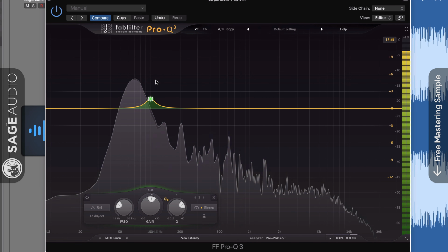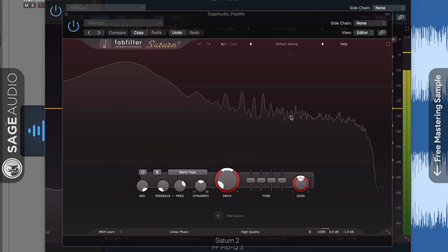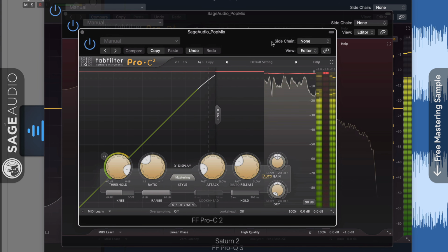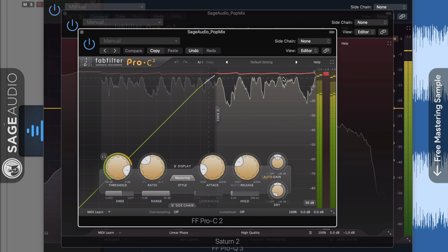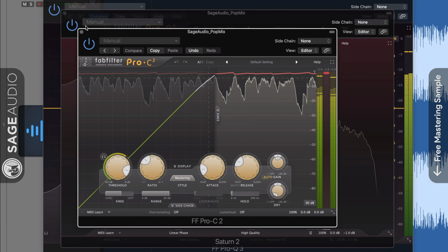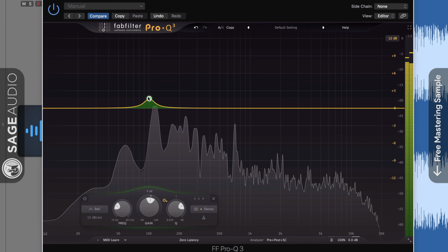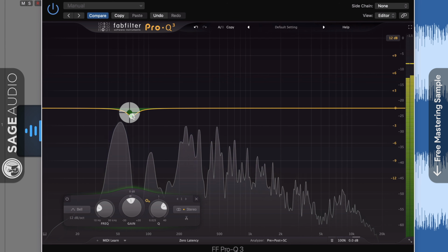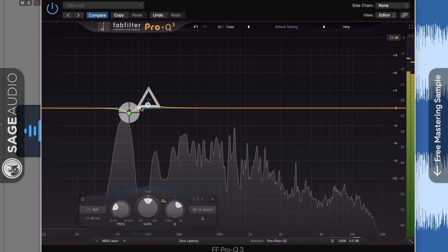Secondly, that 100 Hz wave is now running into the next stage of processing a little more aggressively. For example, if the next processor is a compressor, then 100 Hz will play a more significant role in how much is compressed and when the signal triggers the compressor. Again, this may not be something that you want. Instead, what we could do is attenuate frequencies below 100 Hz.